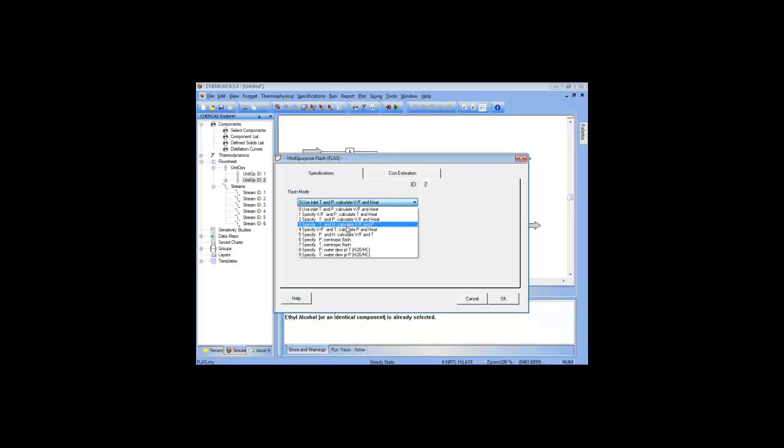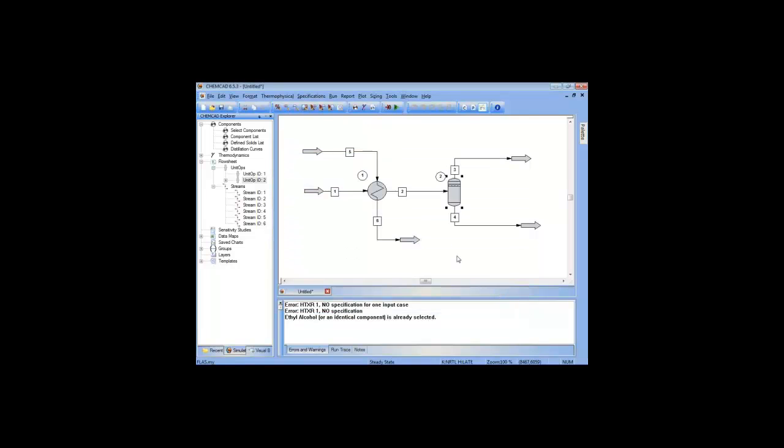Change the pressure and then recalculate. Or specify a particular vapor fraction, and have ChemCAD figure out what else is needed in order to have that happen. In reality, that's probably more than one unit operation. You might need a heat exchanger and a valve to drop pressure and some things like that. ChemCAD doesn't necessarily care about that. It's just doing a thermodynamic calculation of what thermodynamically would happen or be needed in order to satisfy that.